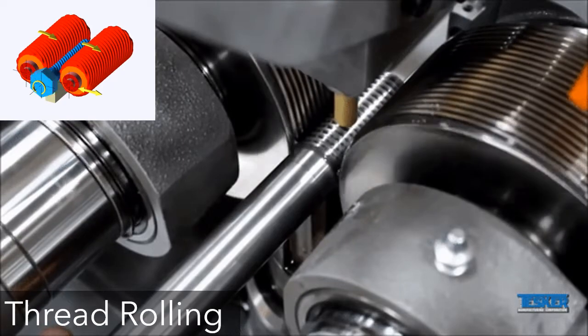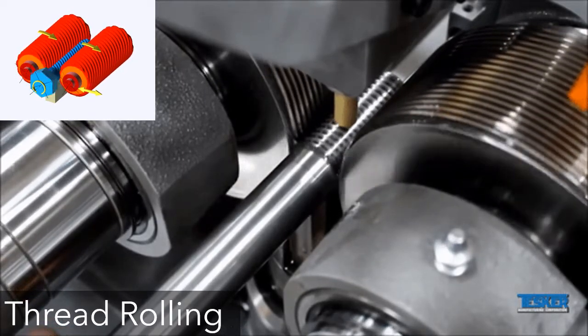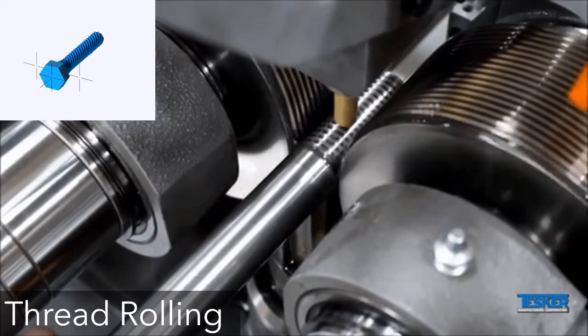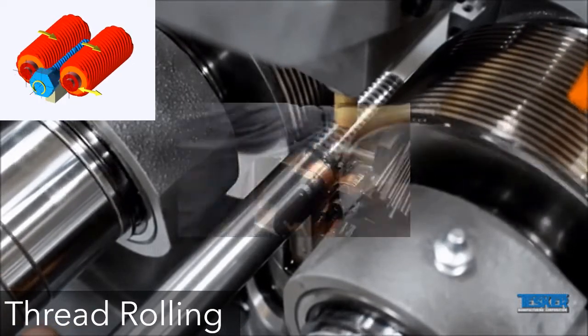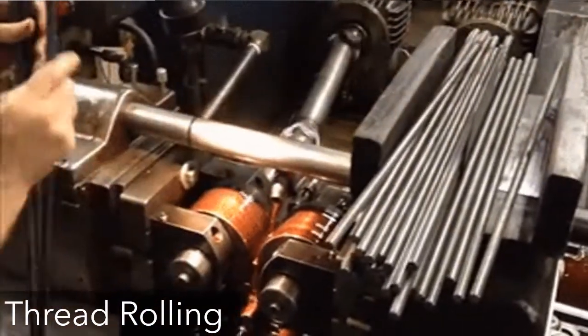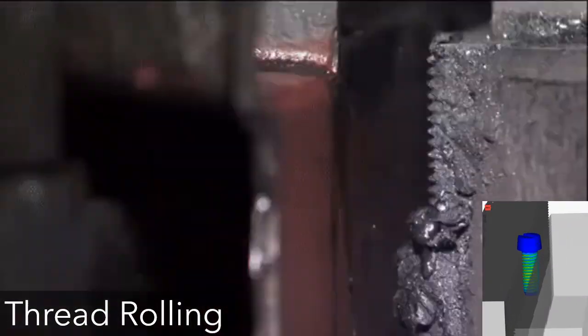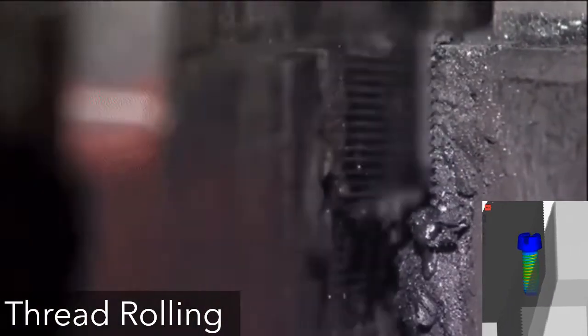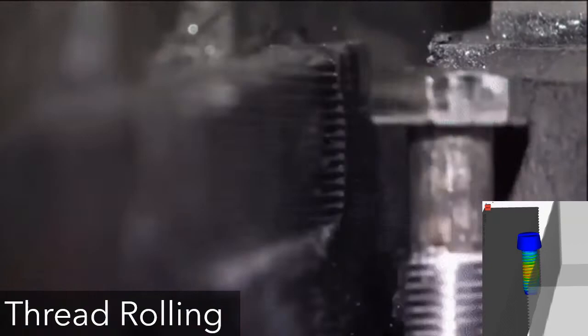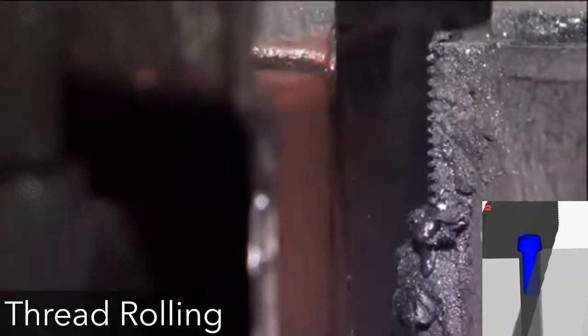Thread rolling is a metal rolling process used extensively in the manufacturing industry to mass produce screws. It is important for mass producing bolts and screws and is performed as cold working in a thread rolling machine. The main advantages over thread cutting are the high production rate, better material utilization, stronger threads, and better fatigue resistance.